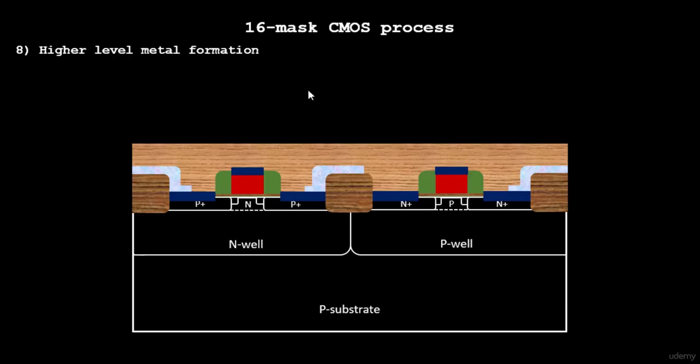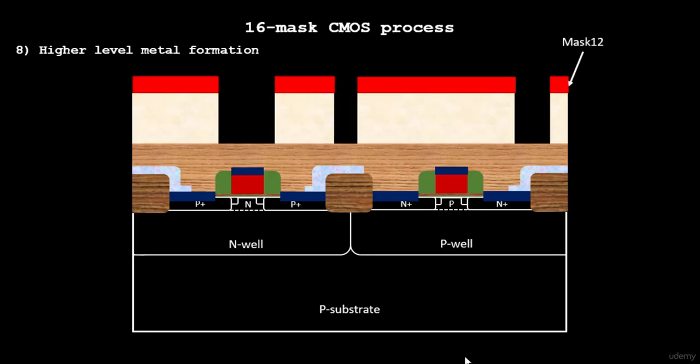So what happens when you do that? The particles of the titanium metal will get sputtered out, will get removed from the titanium, and it will get deposited onto the substrate. These are all very controlled experiments that we do. The metal atoms on the surface of the titanium are being hit by the argon gas, and they are emitted and get deposited on the substrate. This process is called sputtering.